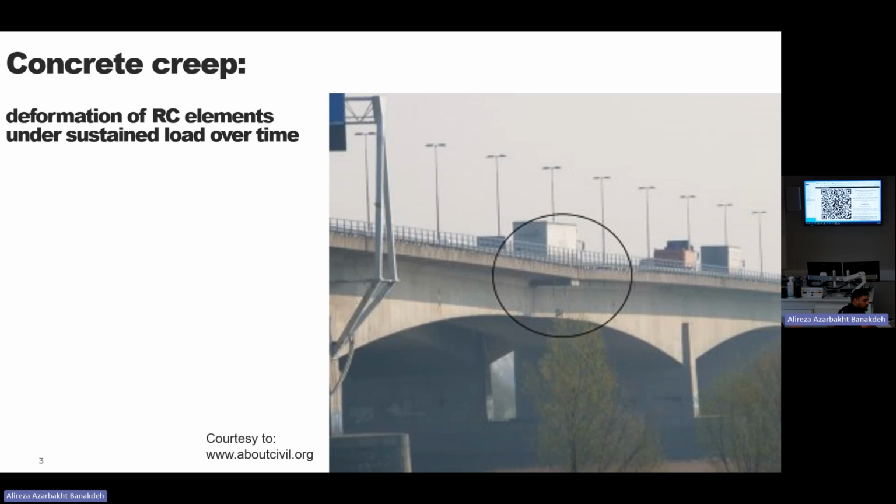Is that why when you typically dry pack the areas, or you fill in an area which hasn't been cast by the concrete, you wait 2 days for it to shrink? No, you need to cure it for 20 days at least. Cure means that you need to make the atmosphere, the surrounding area, moisturize it to help, because the inherent water, the concrete needs that water. If it gets dry, it will not get to the maximum strength that it should get. So it's only about 28 days, okay?